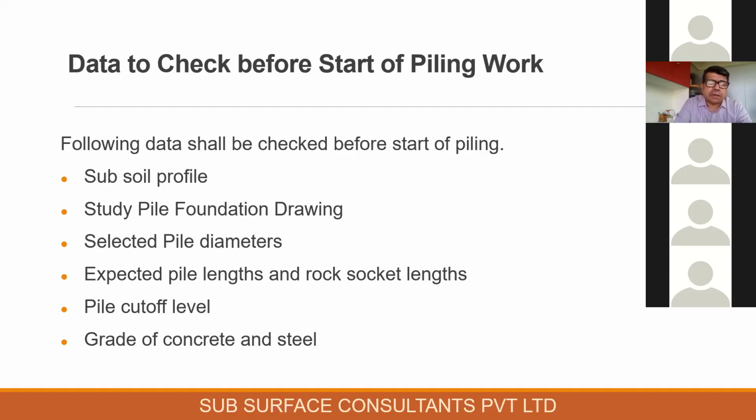Please remember that pile foundation work has to be done from the leveled ground level, and excavation has to be done only afterwards. Many times the developer comes back to us and says, let us first excavate, and after excavating we will lower the machine into the pit and do the piling from there. But such a plan is very hazardous because the muck that comes out of the pile holes cannot then be carted out. It becomes a very big headache because even water may come inside. Considering those things, it is important that the pile cutoff level has to be defined.